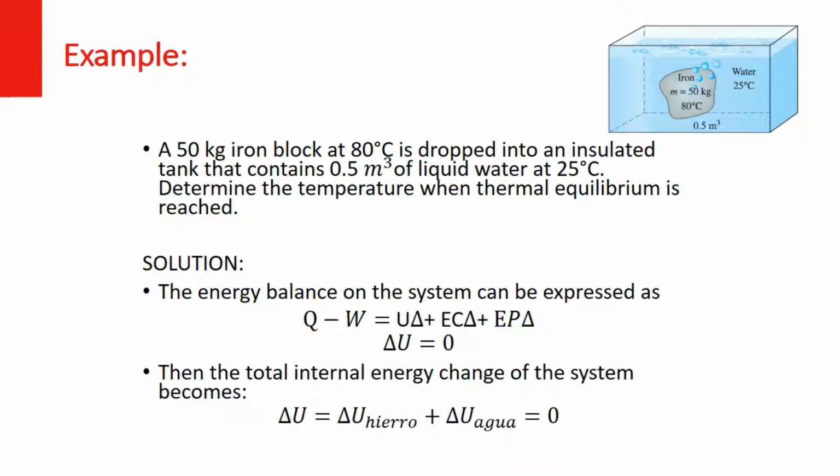We take the entire contents of the tank as the system. This is a closed system, since no mass crosses the system boundary during the process. We observe that the volume of a rigid tank is constant, and thus there is no boundary work. But there is no work or heat transfer, and the system is stationary.